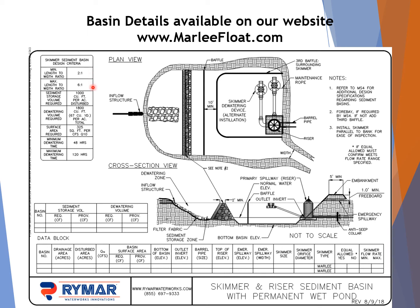We have the same sediment basin criteria. We just simply add a sediment storage volume requirement. Basically everything else is similar. We added a block for the sediment storage volume and dewatering volume. Again, your required should be less than your provided, and your provided could be much greater, but you want to make sure that your design is based upon your required.